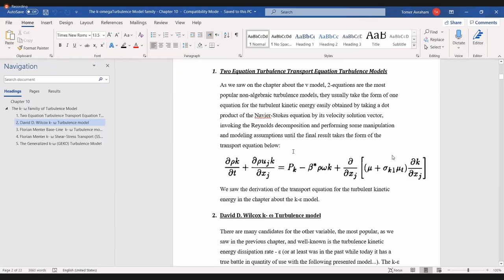You can solve the drag if you're deciding to use wall functions, and you missed the non-slip condition, or you decide to use some kind of what they call the low Reynolds model, which at the time, and we can still call it that way, the Van Driest damping function, a very nonlinear function, which makes the solution a lot stiffer.